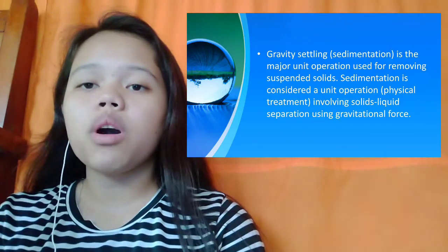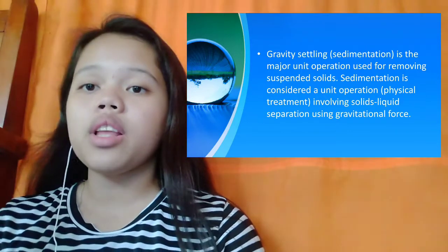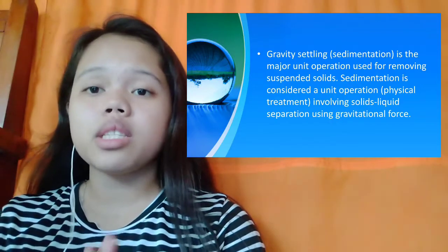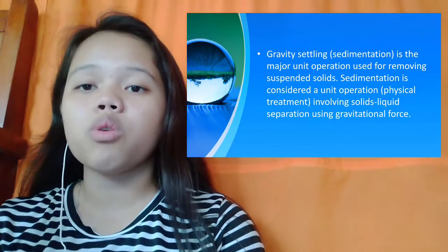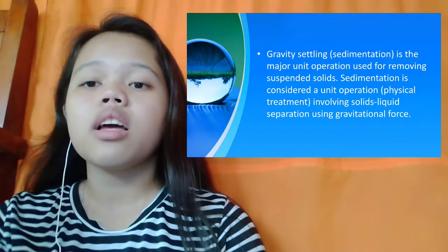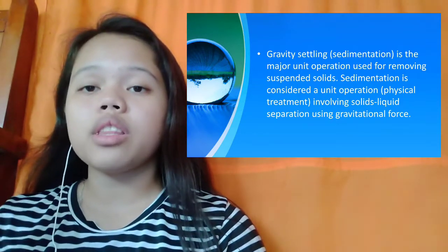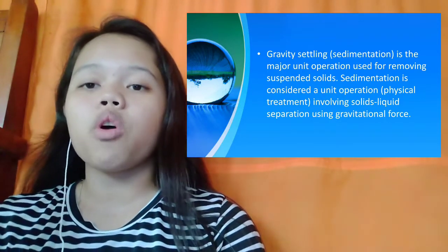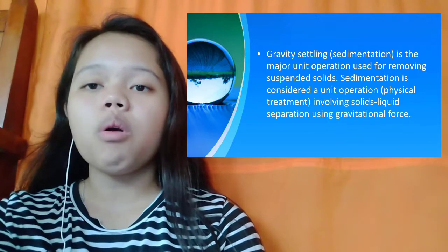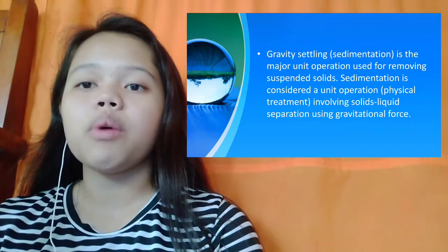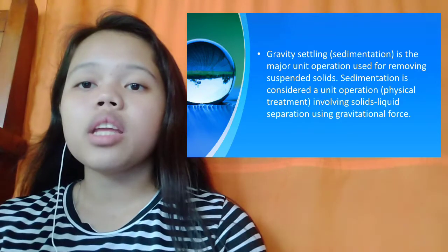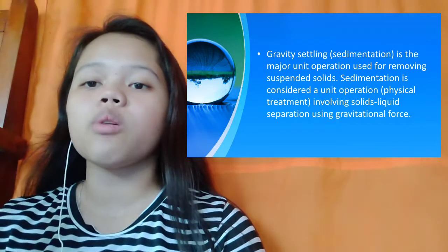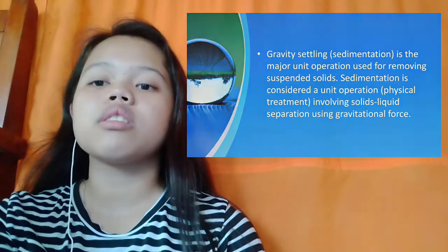Surface water will contain turbidity in the form of colloidal and suspended solids that must be removed from the water. If the raw water contains turbidity greater than 1000 NTUs, pre-treatment in the form of plain sedimentation is typically accomplished before proceeding to coagulation flocculation processes.